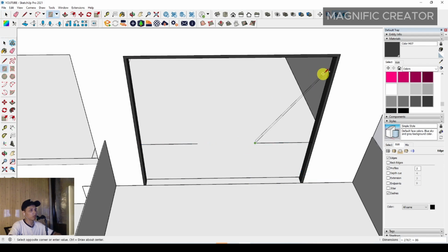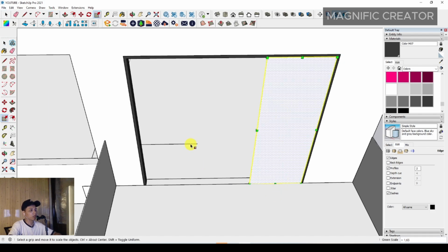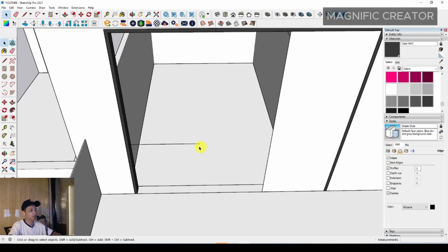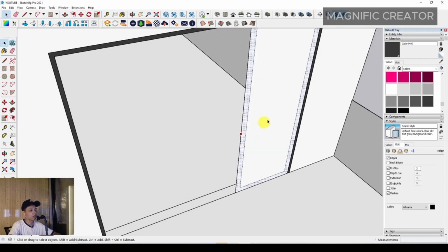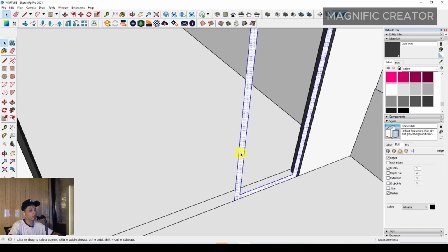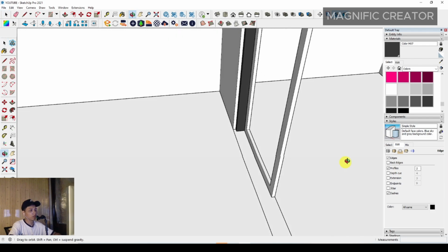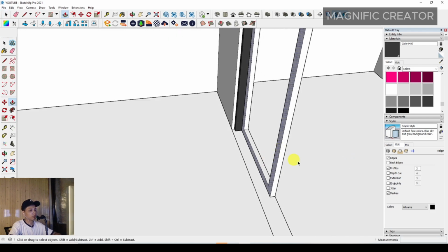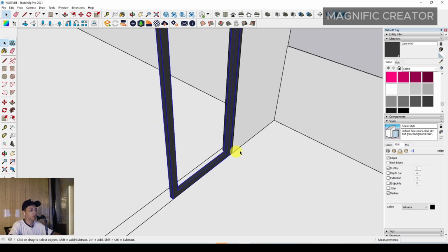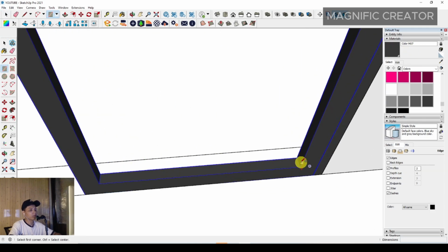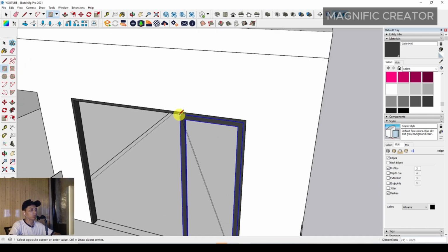Okay, and then we can make a rectangle and just scale it, and offset it inside. We can erase it, and then we can triple click and give a thickness with push and pull, for any size as proportional as possible anyway. We can set the glass with a rectangle anyway.